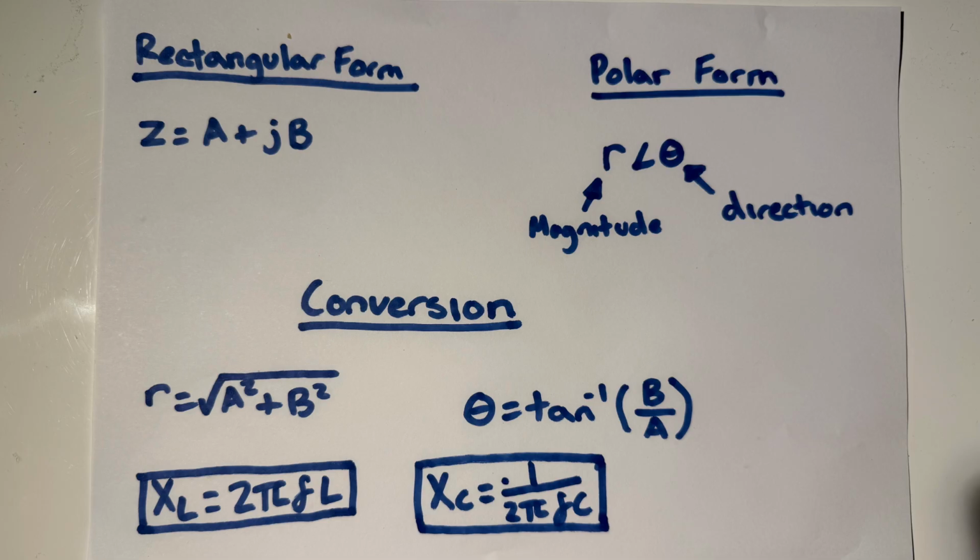So here, since we have alternating current, we use vectors and not scalars. R represents the magnitude and theta represents direction. This is the polar form, which means it can also be written in rectangular form. Using the two equations listed below, you can convert from polar form to rectangular form or vice versa, depending on what suits. Usually, polar form is better for multiplication and division of impedance, and rectangular form is better suited for addition and subtraction.